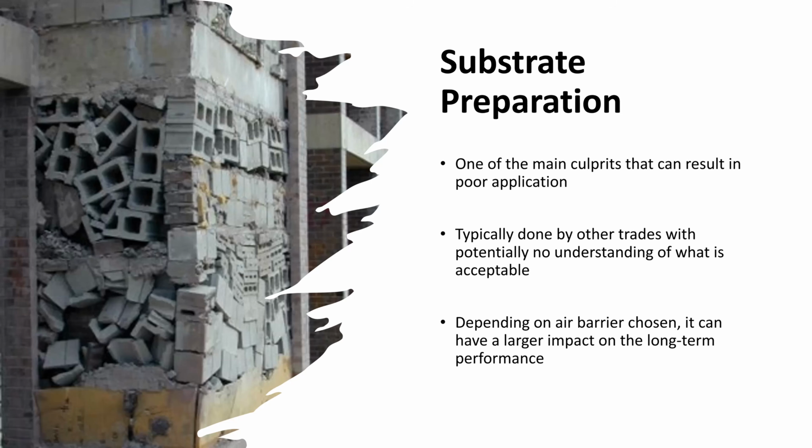And so the manufacturers of these materials will have very, very specific instructions in regards to what the substrate needs to be in regards to it being acceptable. And when I'm saying acceptable, this is specific to materials that rely on adhesion, not mechanically attached, right? If you are mechanically attached, some of these things aren't going to play into the grand scheme of things. It's more things that rely on actually having to stick to something.